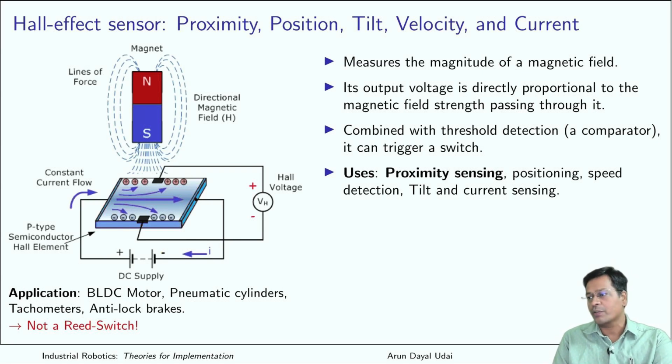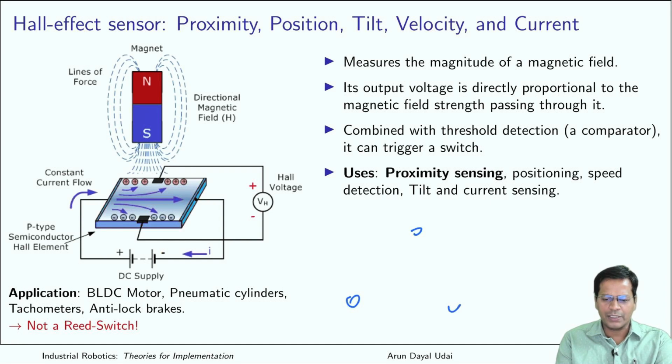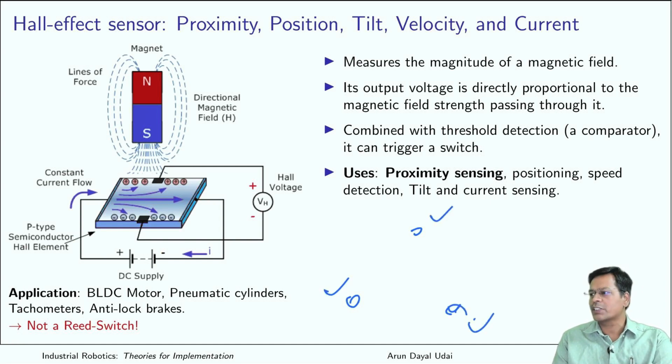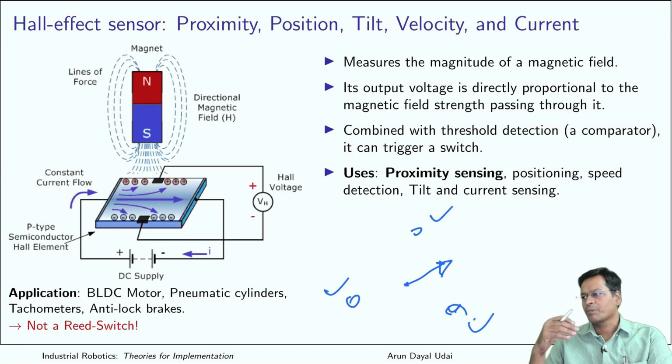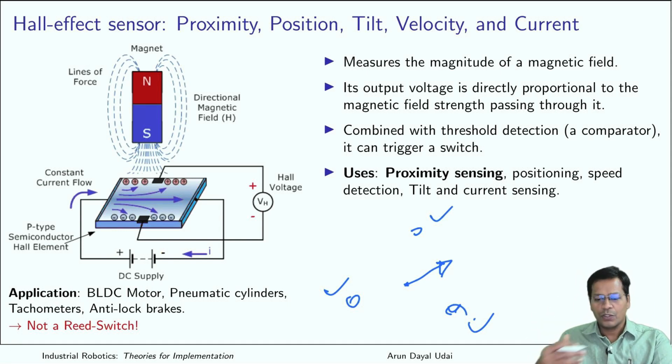And now, how the position of the shaft, that day you got using the BLDC sensor, you had 3 of them fitted in the BLDC, in between the coils. Based on the strengths of the signal coming from all 3 Hall sensors, you were able to determine your rotor position, at least to some precision. So this is how you can detect the position also.